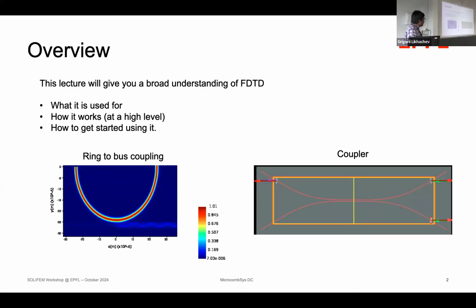This lecture is divided into two parts. One is before lunch, where you'll see how to simulate a directional coupler based on evanescent waveguide coupling and coupled mode theory. Then we go for lunch, and after lunch, we will look at how to simulate a bus-to-ring and ring-to-bus coupling section. These are the terahertz ring devices that generate microcomb sources. That would be after lunch.